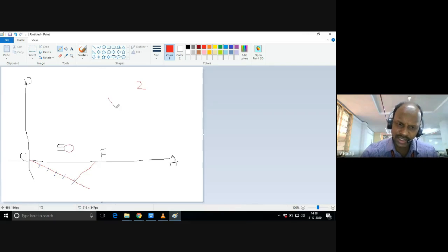Your mini drafter has a 90-degree scale, right? So it will be something like this. You can match the longer edge of that scale here. Tighten the mini drafter. Just move the drafter, and automatically you will get parallel lines like this.